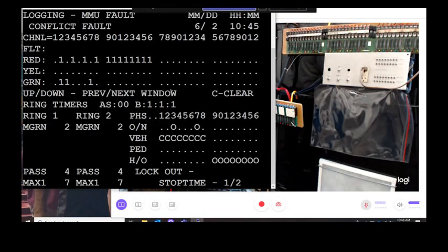Again, going by my load switches, I had load switch 3 and load switch 7 was green. So you see the 1 on the bottom line is green and green. But you'll also notice that there's a green under channel 2. There should only be a 1 in each column. So if you look at all the other columns, there's either a 1 on the green or a 1 on the red. For channel 2, there's a 1 on the red and the green. So that's going to tell me that my problem is in channel 2 green.